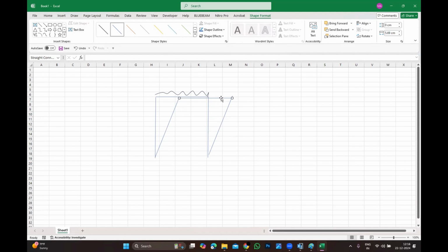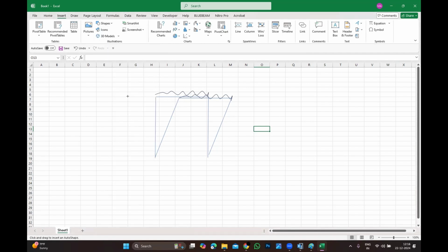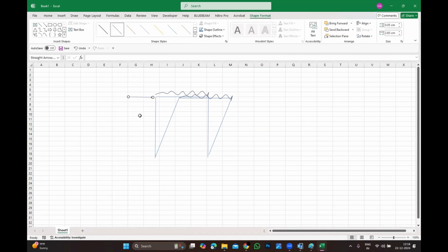Yeah. This is the sway. Okay. What happened? This gravity load goes here, isn't it, if it sways. When you do have lateral force, either wind or seismic, wind will come from here, seismic will come from here. Seismic is going to come from below ground.